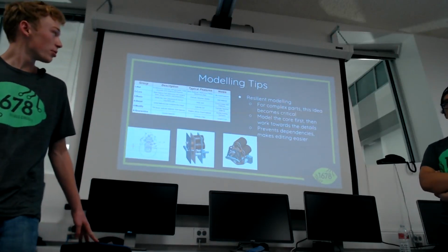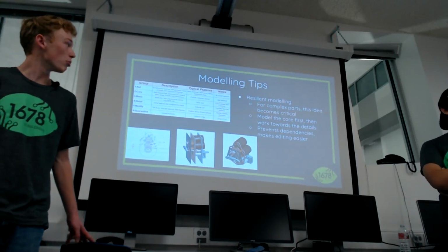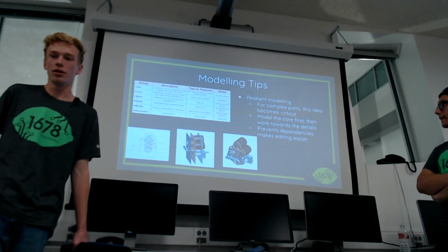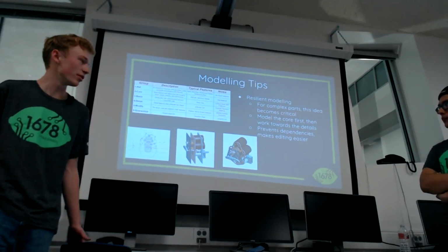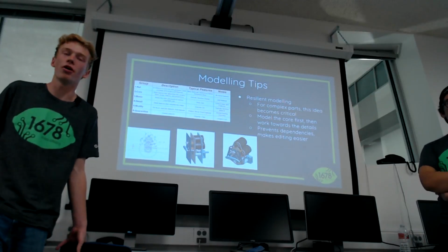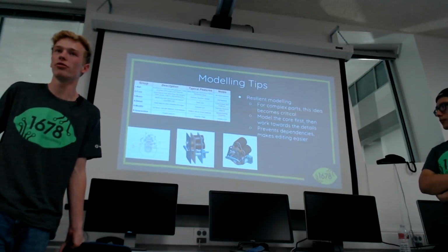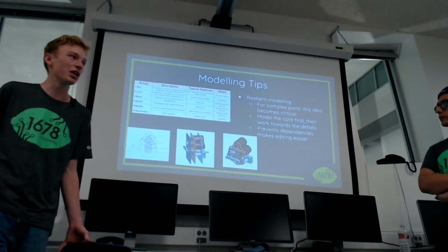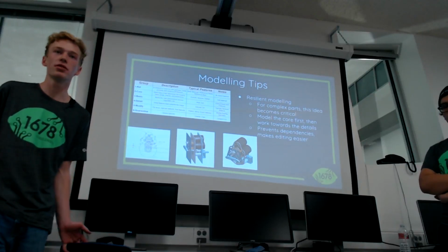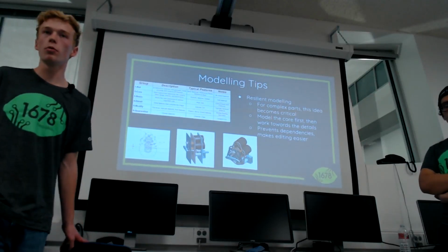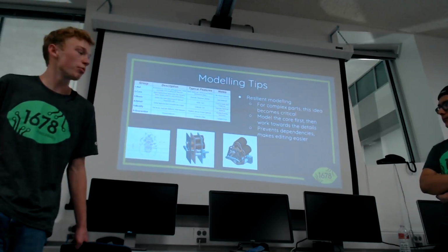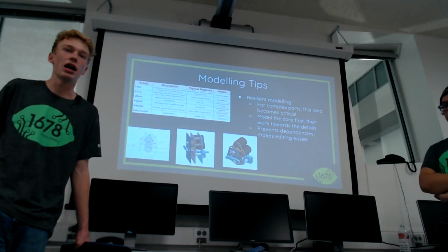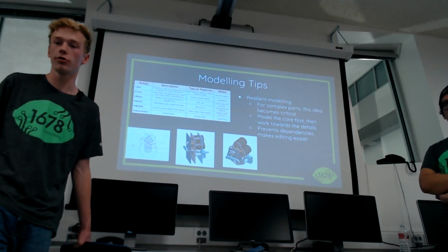So the first concept I wanted to talk about is this idea of resilient modeling. In the past, I have modeled a couple of 3D printed parts with over 100 individual features in a single part file. And when you have that many, it can be a huge pain, and you need to have some kind of organization. One way of organizing these parts is resilient modeling, which basically just means that you can go back and edit it at any time, and you'll still preserve the structure of the part.